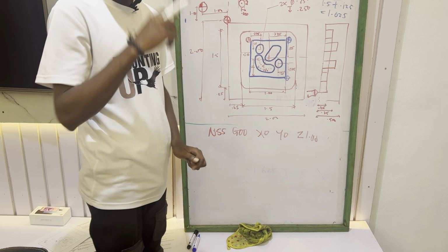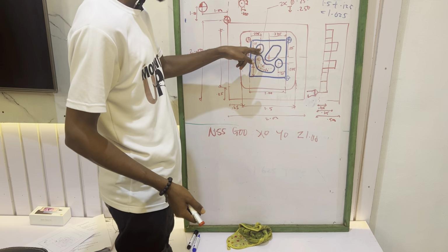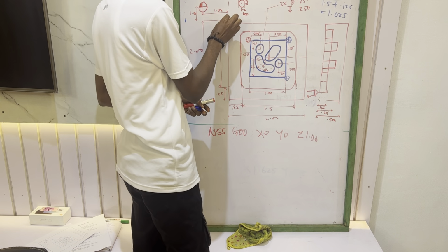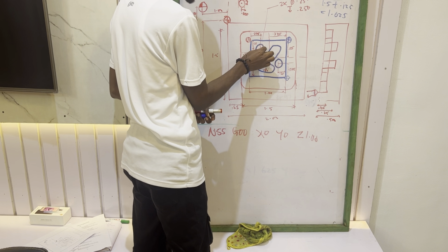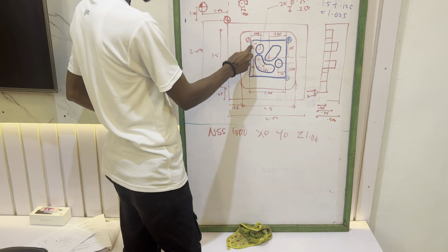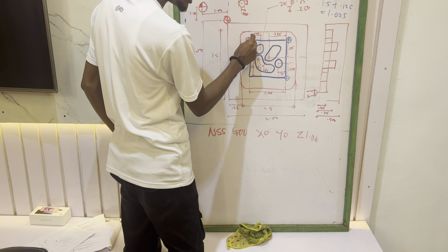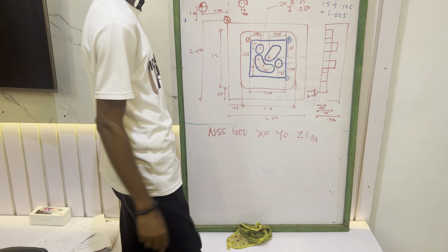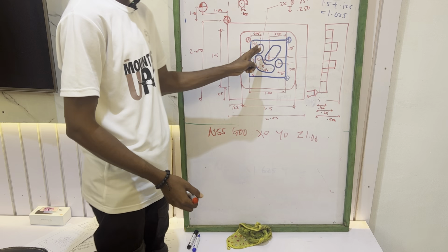So we have done rapid positioning. We want to perform the next operation. What is the next operation we want to perform now? It is to drill this hole. So we have to locate the coordinates of this hole. If we now take our tool to this particular position, where do you think this position will be located? Trace it. You will see that here is 0.25, here is 0.25, and from here to the center of the O is 0.375. That's 0.25 plus 0.25 plus 0.375, which will give you 0.875 towards the x axis.